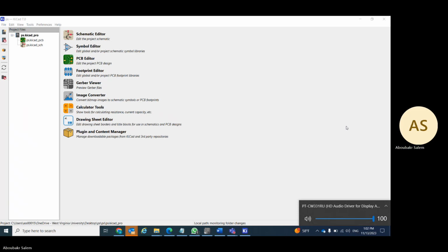Zener diode for what? But Zener diode is doing the regulation function. But since we have regulators, so we don't need in this case Zener diode, because the Zener diode circuit will have a very limited current compared to the high current power supply. Okay, because for a Zener diode, you have to have a series resistance, correct? And if you have high current, this series resistance has to be high power. Okay, which is expensive, generating a lot of heat, and not recommended. So instead of using Zener diode, we can use regulator instead. Okay, so the regulator can solve this problem.